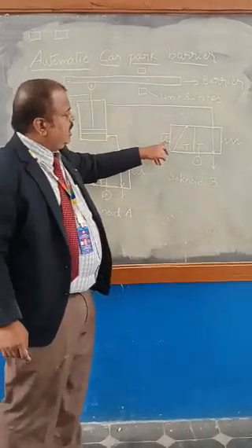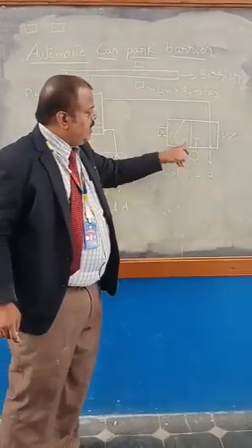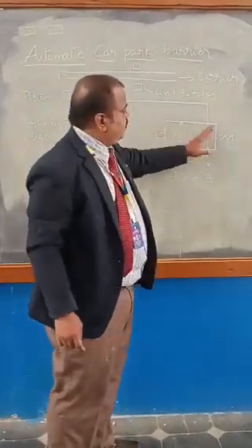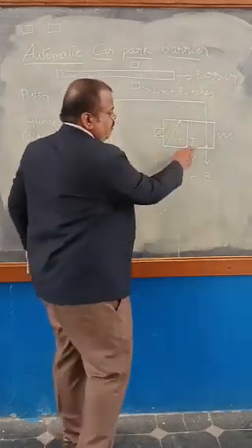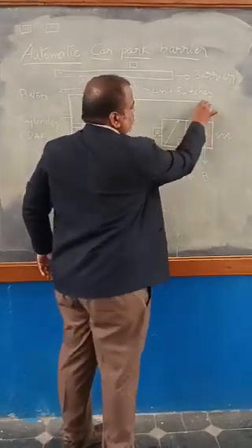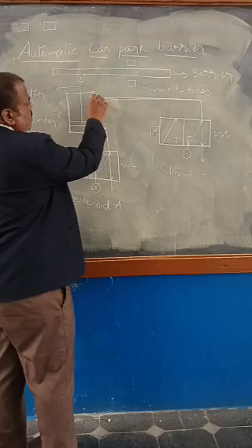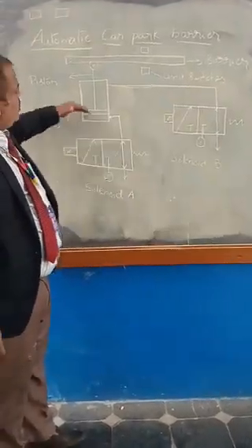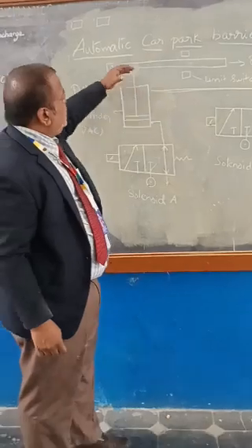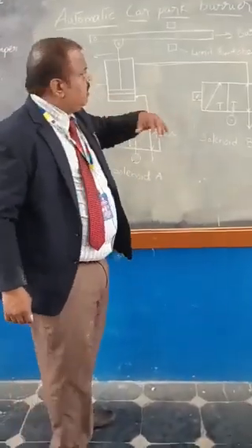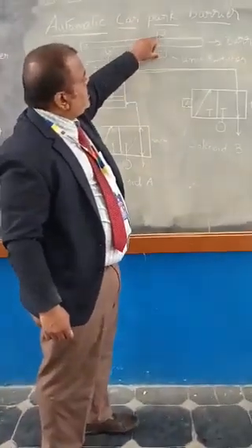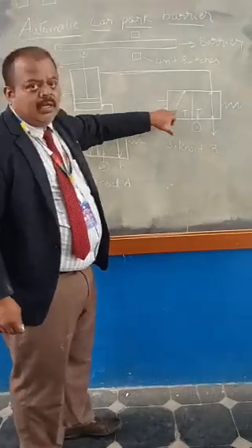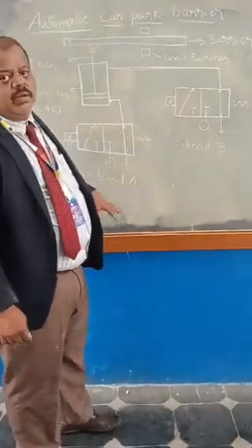So next, once the vehicle moves past, what will happen? This solenoid gets energized so that it will change the position. When it changes the position, this pump will pump the air so that the air moves towards this direction. So it pushes the piston down. When the piston moves down, it brings the barrier down. When it reaches the limit switch, the signal will cut off to this 3x2 solenoid.